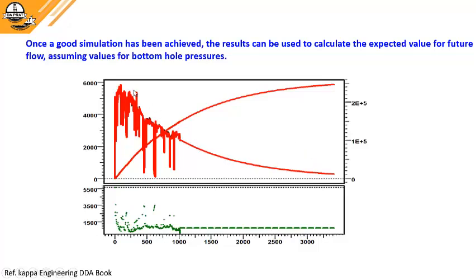So what you do, you get your model by simulation, simulating all this data, rates and pressure, and then from here on you can make, let's say, a forecast.